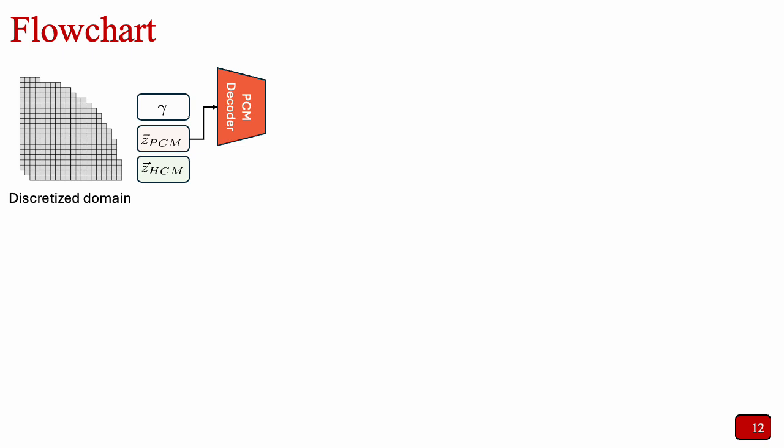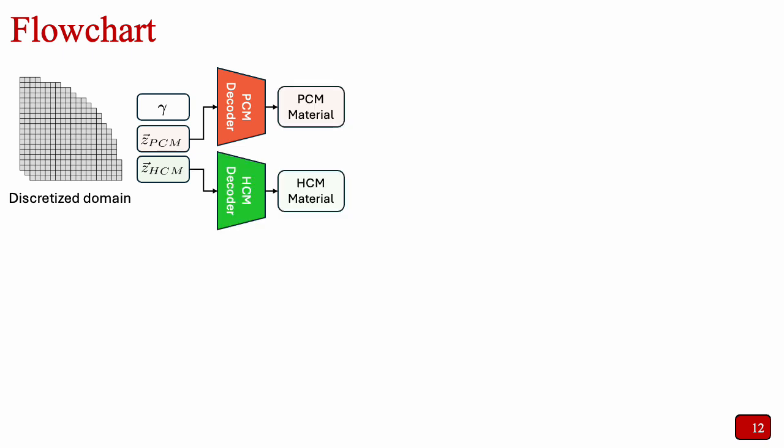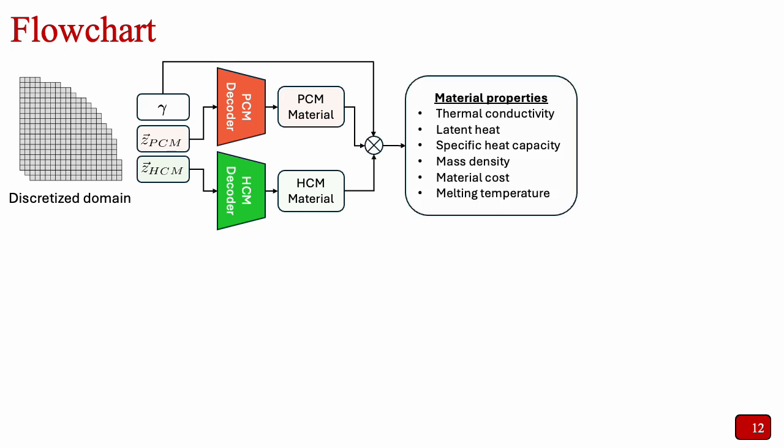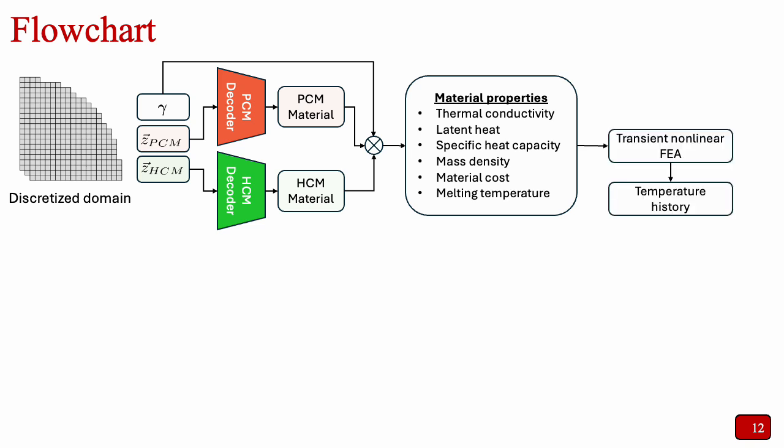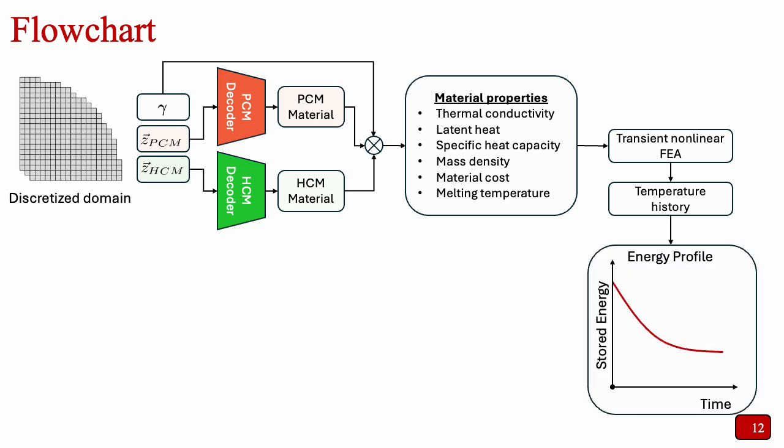The latent vectors are passed through their respective trained VAE decoders. This reconstructs the full list of physical material properties such as thermal conductivity, latent heat, density, material cost, and melting temperature. These properties, along with the density field, are fed into a transient nonlinear finite element analysis solver. This simulation yields the temperature history and the stored energy profile over the discharge time.